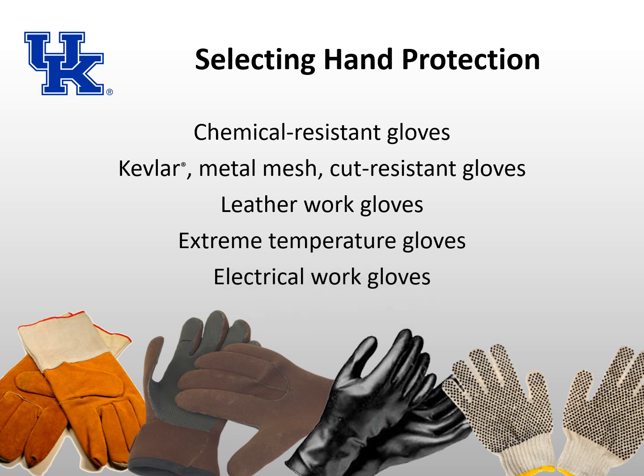Electricians need linemen's gloves designed to protect against different levels of voltage. High voltage gloves are black rubber with red interior so that any cuts or damage to the outside layer can easily be seen. Liners are worn under these gloves to help absorb perspiration.